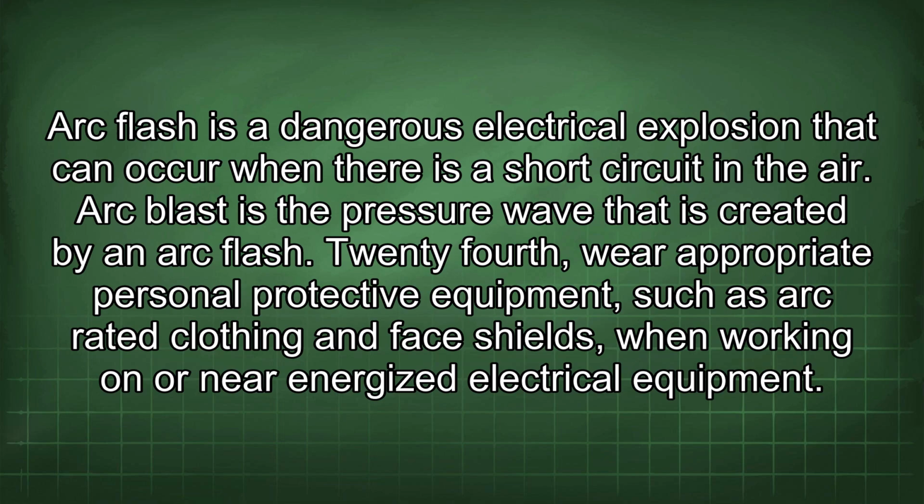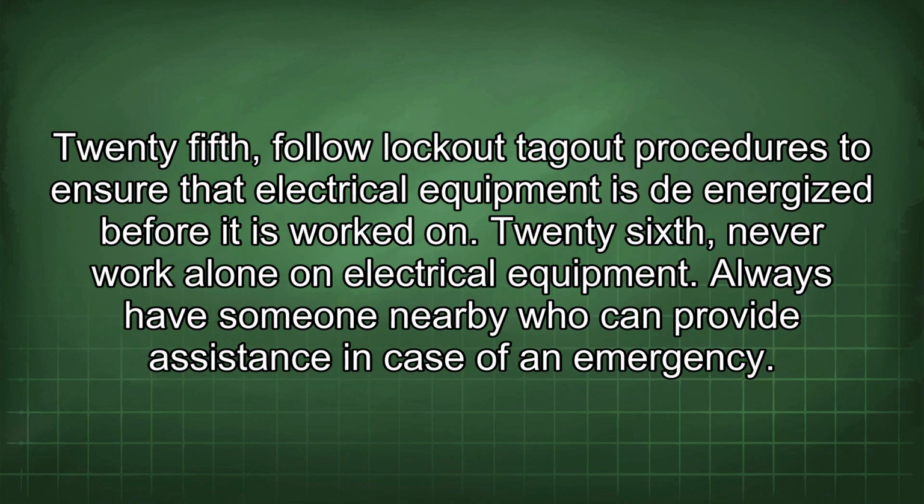24th, wear appropriate personal protective equipment such as arc-rated clothing and face shields when working on or near energized electrical equipment. 25th, follow lockout-tagout procedures to ensure that electrical equipment is de-energized before it is worked on.